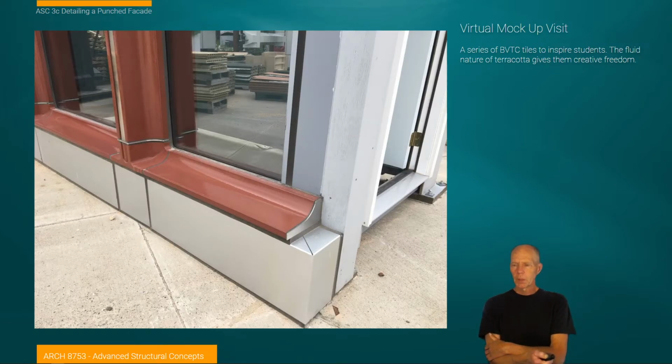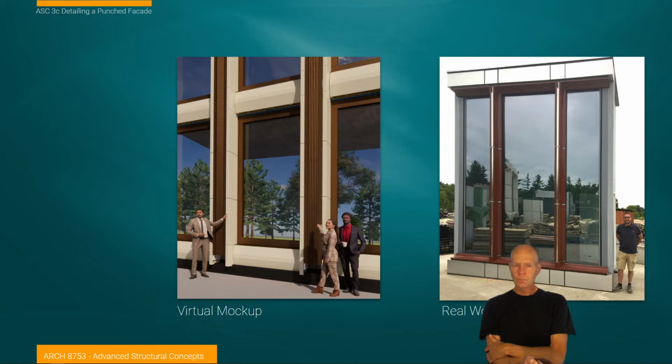Here's one that was part of what's called the ACAW, the Architectural Ceramics Assembly Workshop. The idea here was to use terracotta and put it under tension so that it could actually become structural in glass curtain wall systems. So that's why we have these aluminum connectors at the end. They've got tubes within them, and they're pre-stressing the elements just like you would concrete in order to make them stronger. And actually over my head, that's at full size.